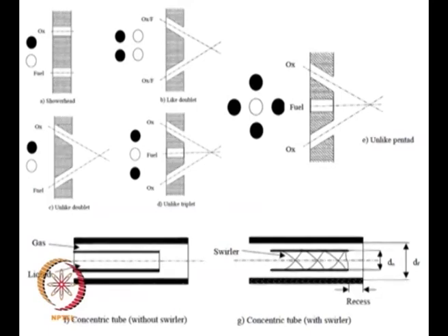Hypergolic fuels, if you remember, do not need any ignition, and once they see each other they start reacting. So in this case you would have heat release very close to the injector head, which sometimes might not be recommended, and therefore whenever people use hypergolic fuels they use the like combination, that is fuel on fuel or oxidizer on oxidizer.